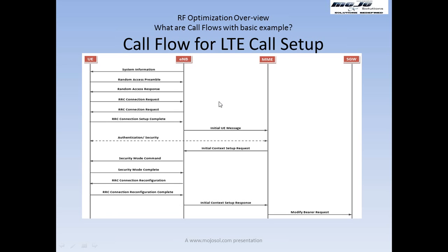How will the UE know, in idle mode, at what level the signal goes off, and at what level I should make a call? If the signal level is too bad, should I make a call? Does the network allow me to make a call at a signal level RSRP of -118? If you don't understand RSRP, trust me, you will not be able to understand this course.